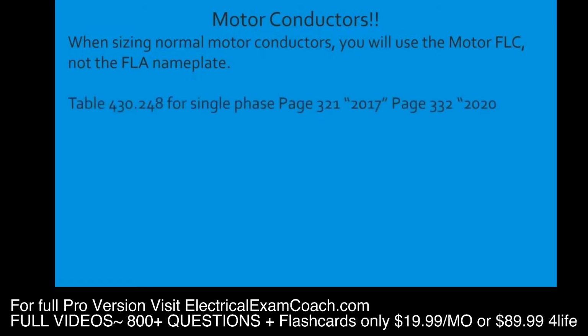We're going to find these values in table 430.248, and that's for single phase. It's on page 321 of the 2017 or page 332 of the 2020. I want you to head there now, pause the video if you need to, and we're getting ready to go over this table. I'll give you a little hint: if you are able to tab your code book, there is a motor FLC tab that will take you right there.